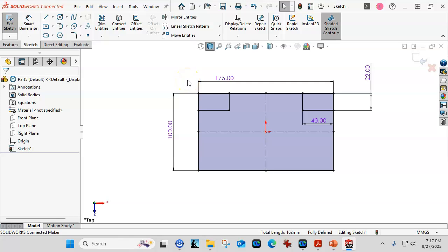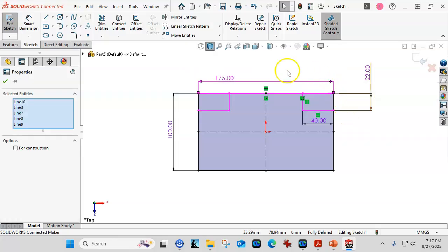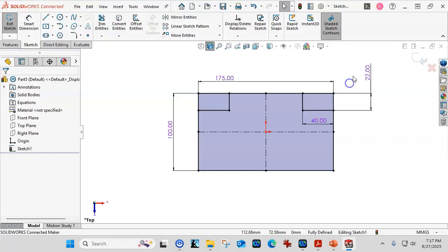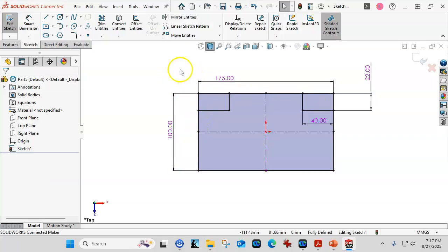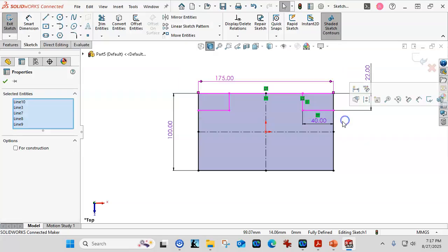Now, on the selections, I don't think I've done this yet. I'm going to window pick. We haven't really needed a lot of window pick yet. If I go from left to right, it grabs everything inside of the window, and right to left, everything crossing the window. I got a couple of things in there that I don't need, so left to right is going to be the better selection.